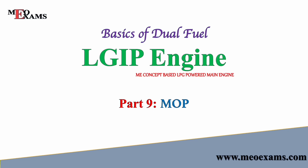So friends, till now we have seen the basics of the LGIP engine. Now for operation of this engine, we have to see a little bit about the main operating panel, that is the MOP. The MOP for this LGIP engine is very much similar to the MOP which is used for the normal ME engines. But a few extra things are incorporated in this MOP for the LGIP engine to change over the main engine from primary fuel to secondary fuel.